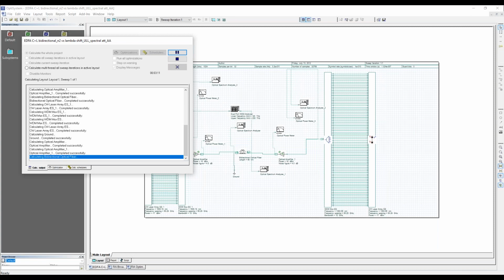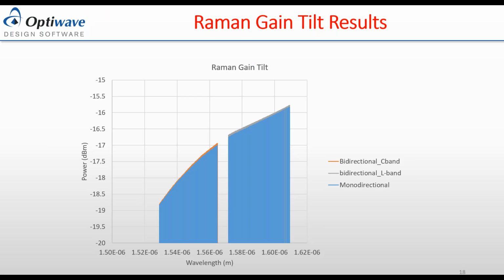The other question we have here is, is the Raman amplifier effect the same in G657 fiber as in G652? Basically, each type of fiber has its own parameters. For us, the important and crucial parameter is the effective mode field area.